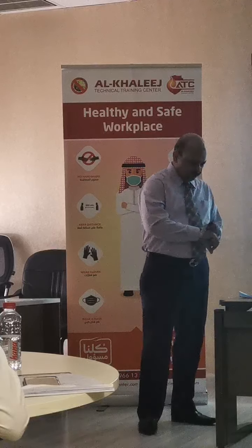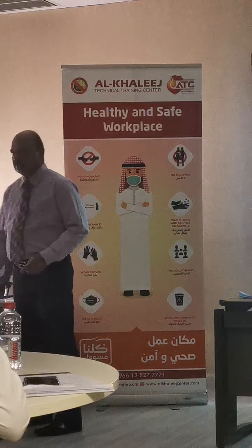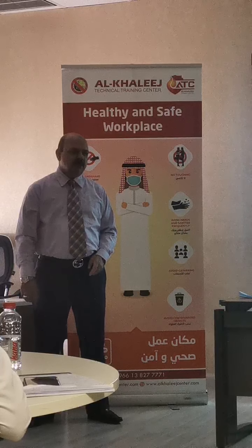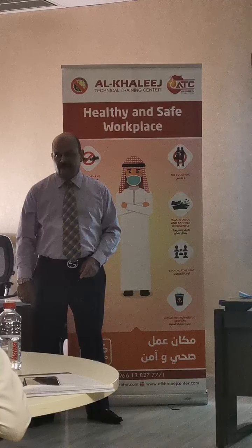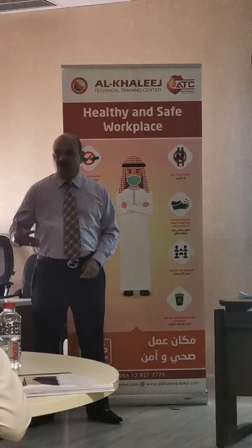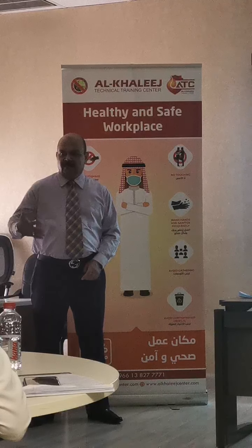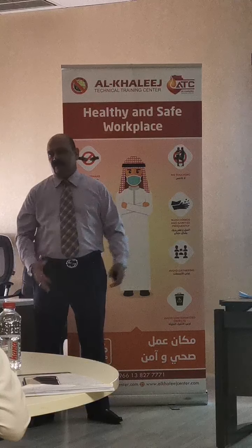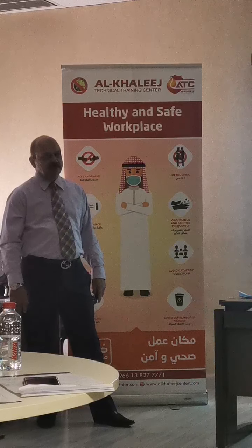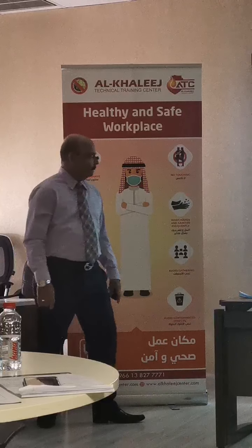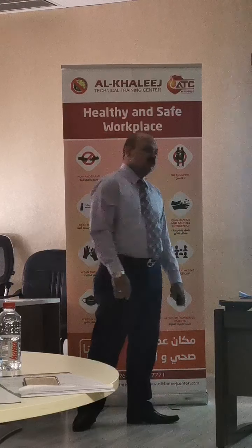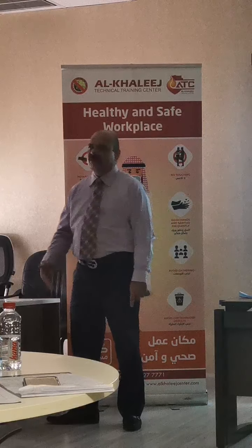Okay, management of change. Again, if there is a change in your material, change in your process, then you need to identify the risks related to that material, that process, that equipment, tool, anything that you change. Change management: a process to be established for implementation and control of planned temporary or permanent changes, even if it is a temporary change or a permanent change.